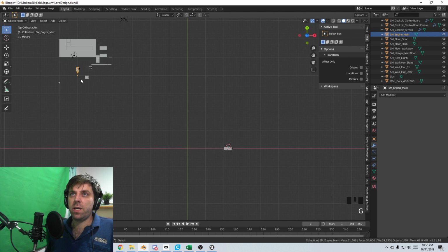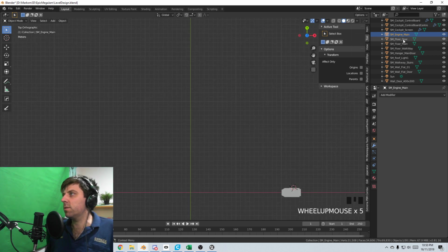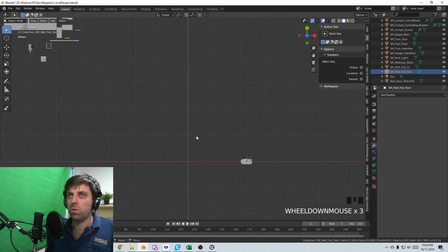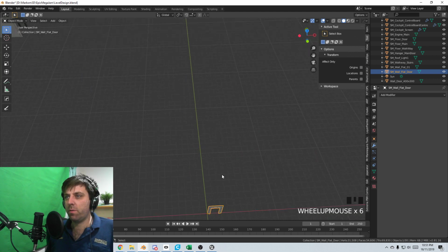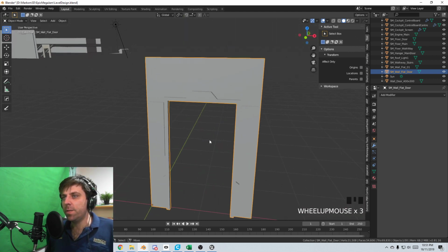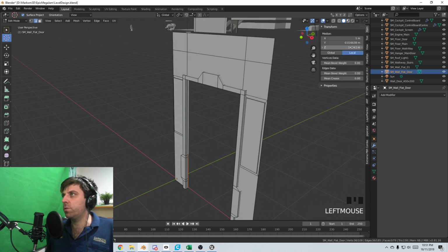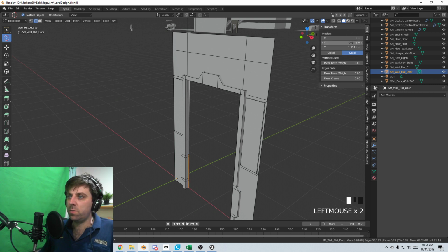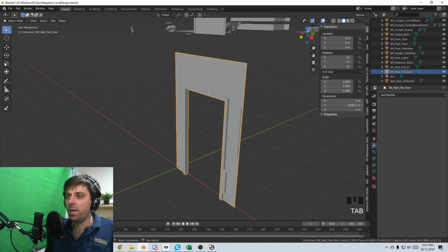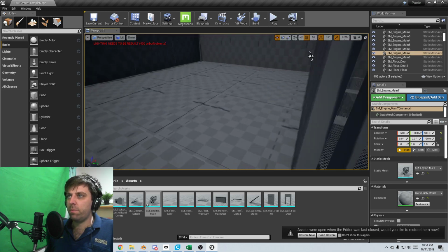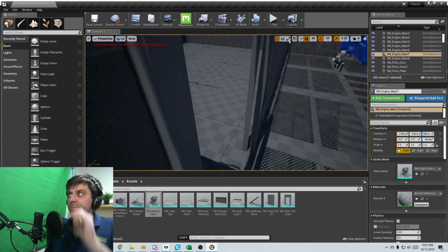Okay, GX. Let's go find the floor, flat door. Now, if I do Alt G, that'll bring me right back. Lovely. What I wanted to do is grab this inside edge and set that to 0. That will fix up this problem.